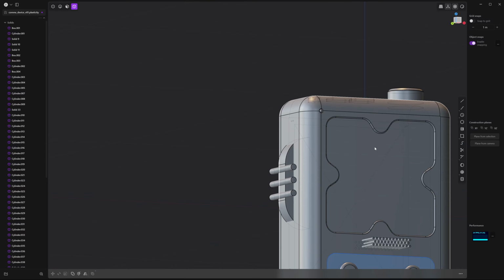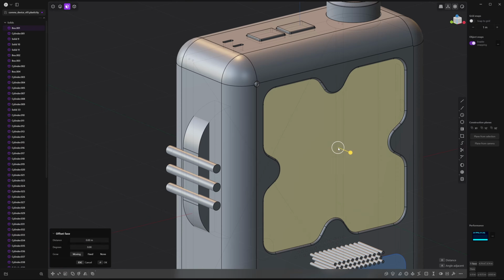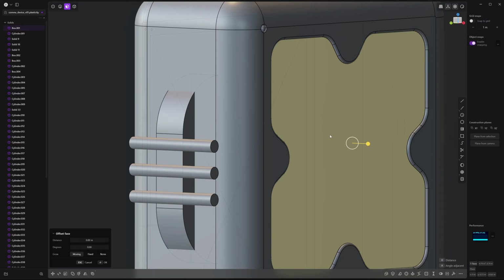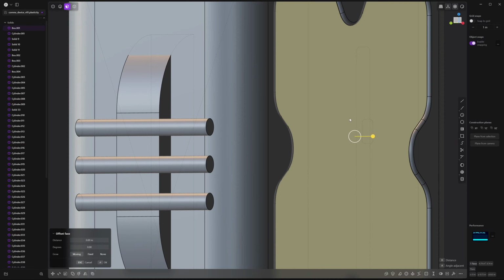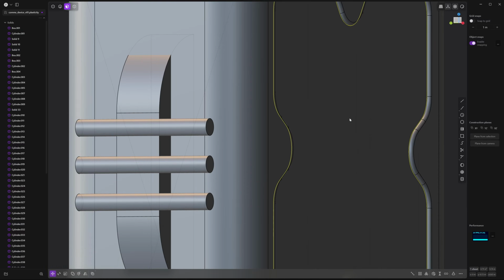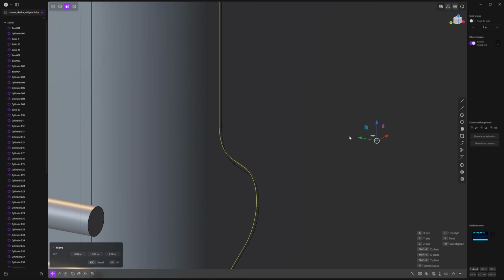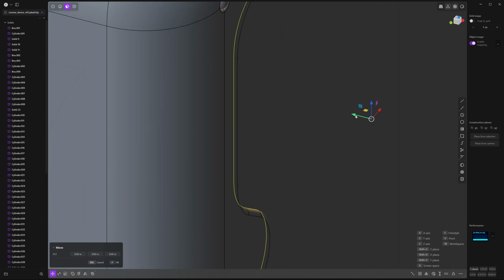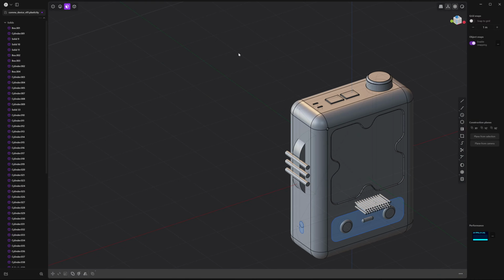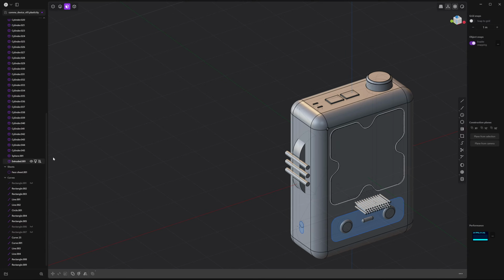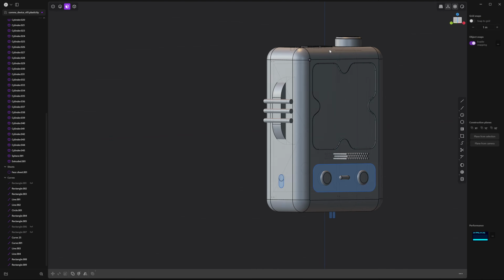Next, I'm just going to hide that screen and press 3 so you can select this interface. I'm going to duplicate this one so that if you take this into rendering, this will be a different piece that you can apply a different material. Press Shift D, and I'm going to move it up on the Y-axis so it doesn't have that Z fighting when it's perfectly aligned with that other face. Bring back our screen in the outliner, just so we have everything.